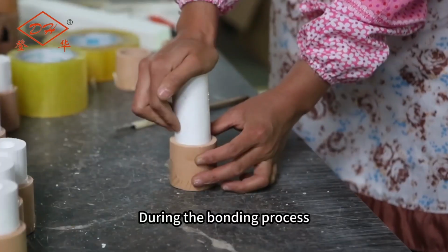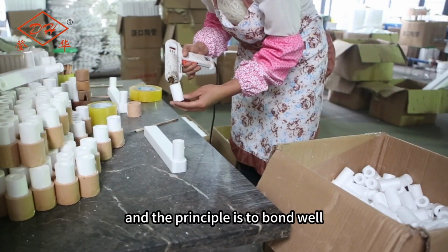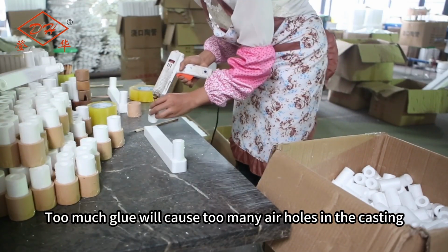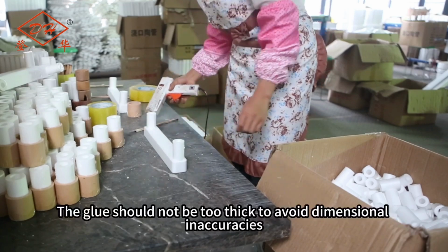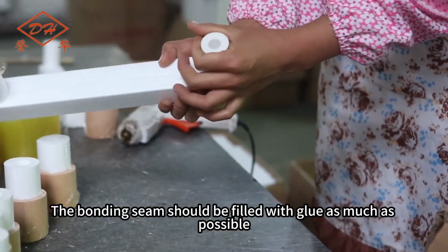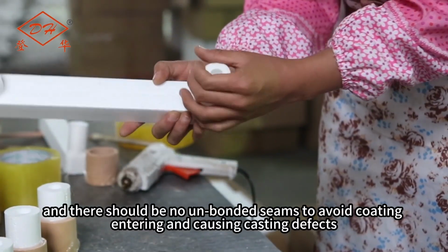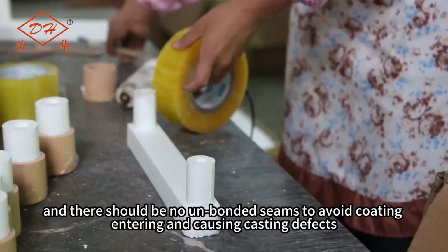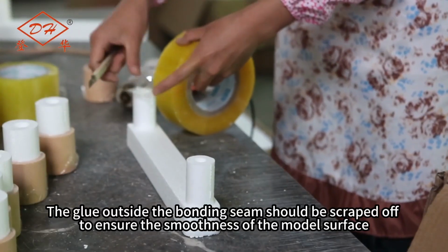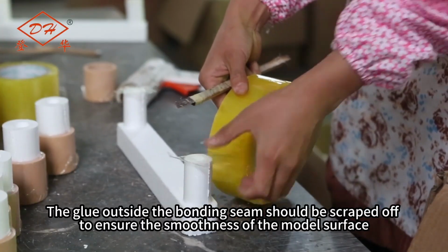During the bonding process, the glue should not be excessive, and the principle is to bond well. Too much glue will cause too many air holes in the casting. The glue should not be too thick to avoid dimensional inaccuracies. The bonding seam should be filled with glue as much as possible, and there should be no unbonded seams to avoid coating entering and causing casting defects. The glue outside the bonding seam should be scraped off to ensure the smoothness of the model surface.